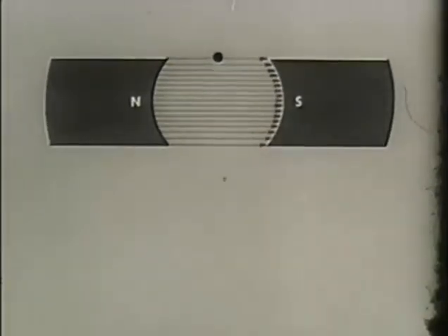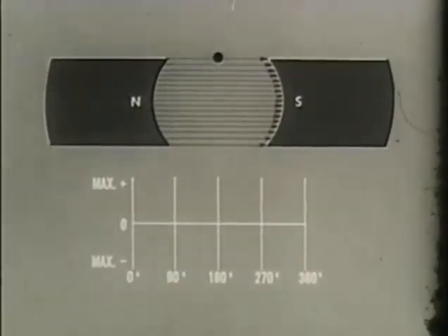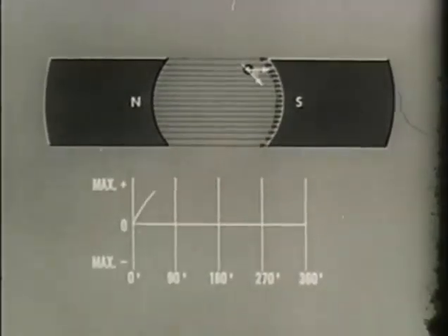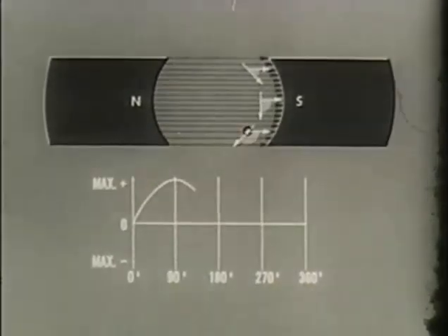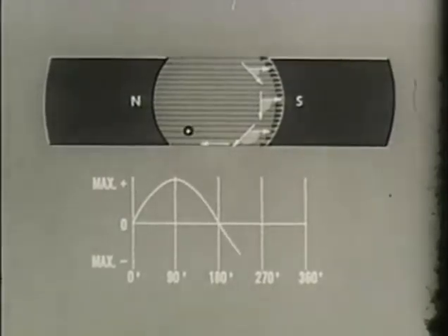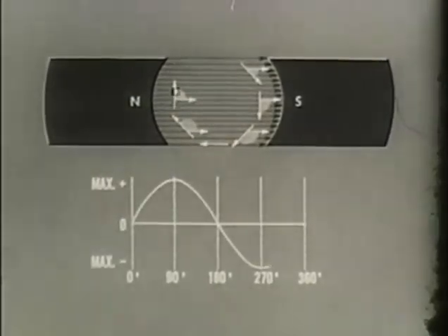Theta is the angle formed by the flux line and the motion of the conductor. The number of lines cut and the amount of EMF generated is proportional to the sine of the angle formed by the magnetic lines with the conductor motion. A graph of EMF versus conductor position during one revolution will be a sine wave representing alternating current, or AC. All rotary generators produce AC internally.